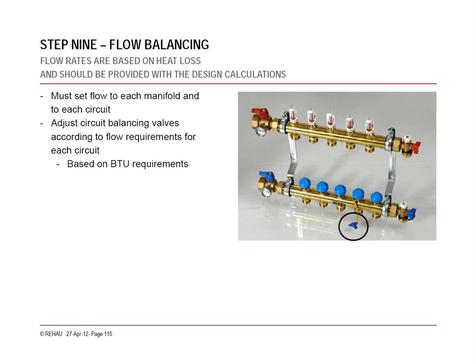If you're using zoning actuators, those replace these little protective blue caps that are shown here on the bottom. So you'll mount those, you'll dial in your flow, and then the actuator will mount right on top of that.